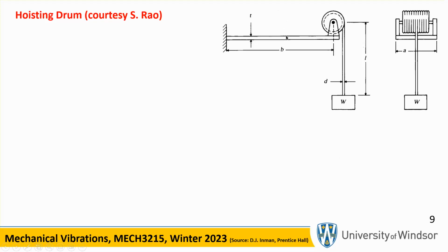One of them is the beam, which we all know what it is, 3EI over L cubed. We just looked at it a minute ago. But there's also this cable that could actually be extensible, and therefore think about it as an axially loaded member, and the stiffness of it we talked about in the last lecture is AE over L. A is the cross section area, E is the Young's modulus of the cable, over L. L is the length of the cable that's hanging.